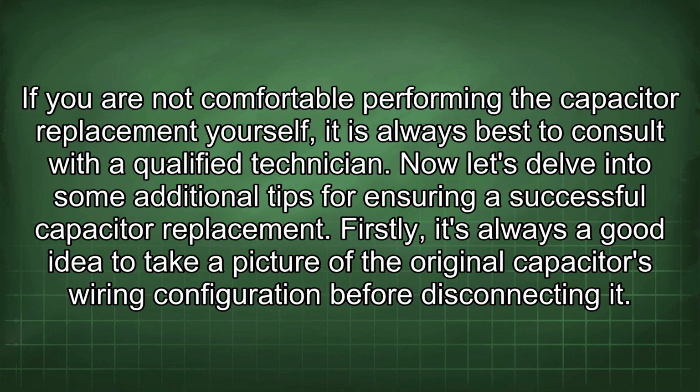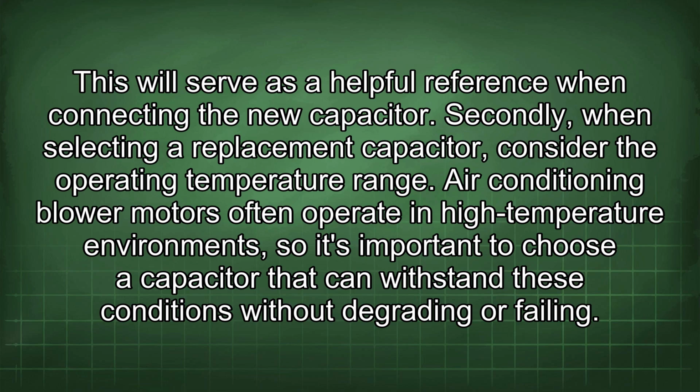Now let's delve into some additional tips for ensuring a successful capacitor replacement. Firstly, it's always a good idea to take a picture of the original capacitor's wiring configuration before disconnecting it. This will serve as a helpful reference when connecting the new capacitor. Secondly, when selecting a replacement capacitor, consider the operating temperature range. Air conditioning blower motors often operate in high-temperature environments, so it's important to choose a capacitor that can withstand these conditions without degrading or failing.